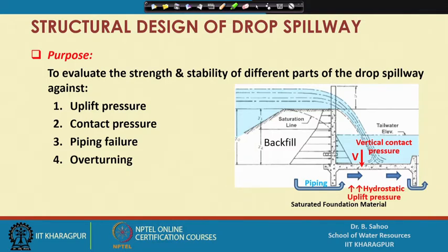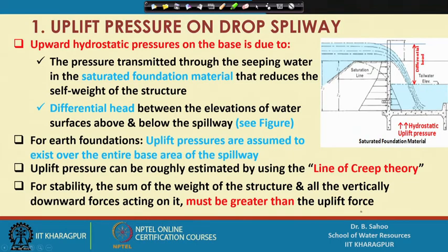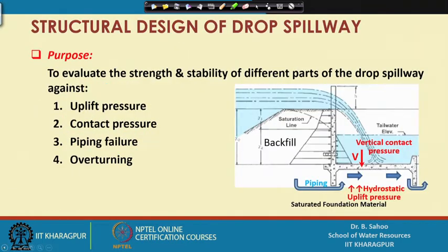What is uplift pressure? The uplift pressure happens because if the foundation material gets saturated, pore water pressure develops, and this hydrostatic pressure acts upward. If this hydrostatic pressure acts upward, then it creates a negative pressure in the stability.